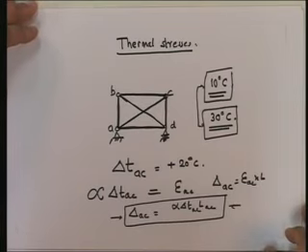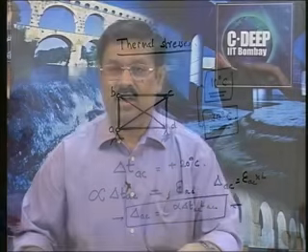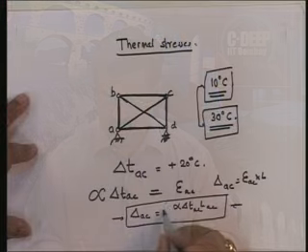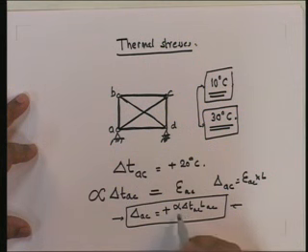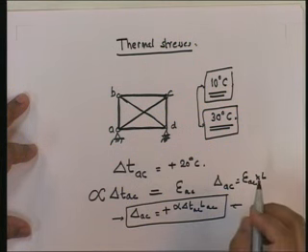So, what does thermal stress do? Thermal stress leads to an elongation, a real elongation of the structure. How will I solve this problem? Well, do you see any difference between this and the lack of fit? None. Again, the real deformation in the member due to thermal stresses gives rise to delta AC, which I can compute given alpha, delta T AC and L AC.